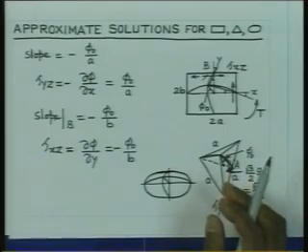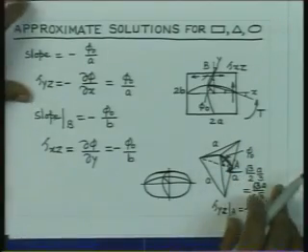And now we would like to look into, you can really go on considering the problem of various types, various cross sections by this analogy, and you can immediately comment upon the point where the stress is going to be the maximum. Let us try to look into some points. I indicated earlier that for a rectangular cross section or a triangular cross section, the stress at the corner is going to be 0. Let us understand why that is so.